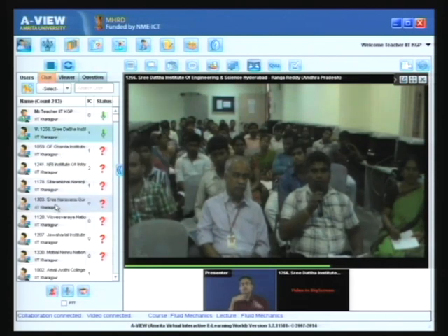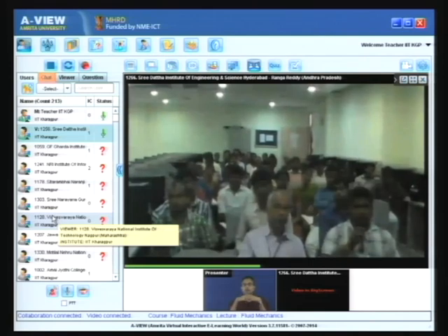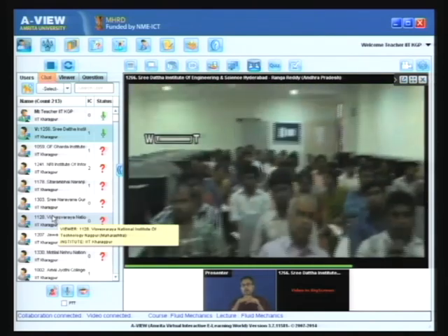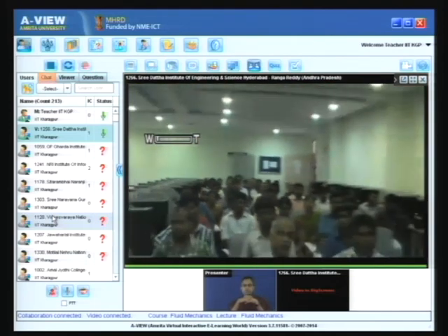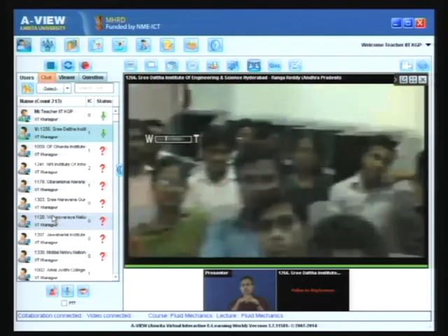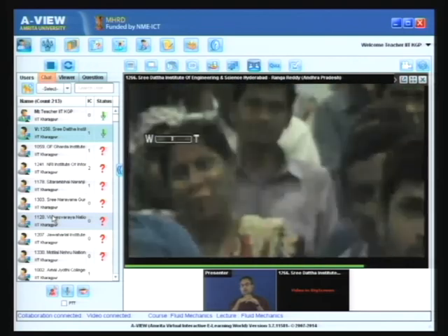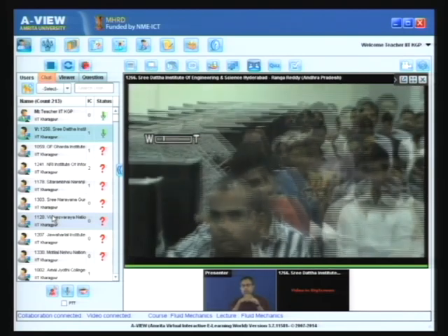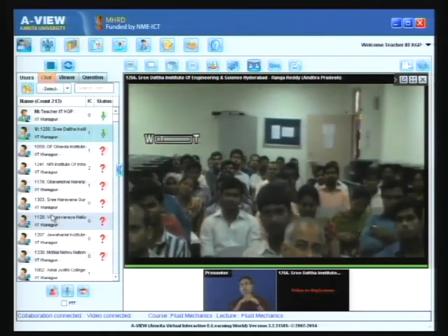See, you will be taught about fluid machines by Professor Som, and there this issue will be discussed. It depends on how thick or thin the boundary layer is, and that depends on the Reynolds number. If the Reynolds number is very large, the boundary layer thickness is very small. Whether the boundary layer effects are taken or not in analyzing a fluid machine depends on several parameters, but one of the most important parameters is the Reynolds number.